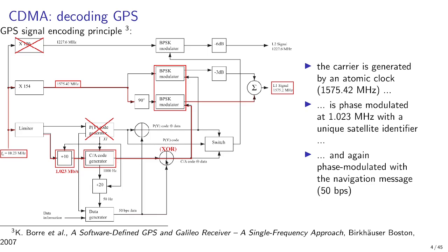XOR is selected because it's a one-to-one relation between input and output. If on the receiver side we receive the XOR message and we know what the code is, then because XORing with 0 is the identity and XORing with 1 is the opposite of the outgoing bit, we can recover the navigation message on the receiver side. These bits are clocking the BPSK input with, on the other side, the carrier frequency, so that at the output of an IQ modulator, the L1 GPS band is broadcast.